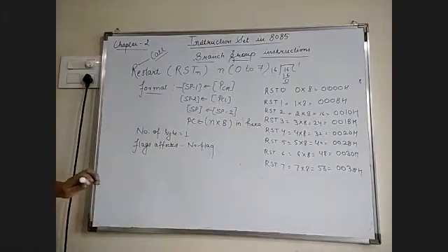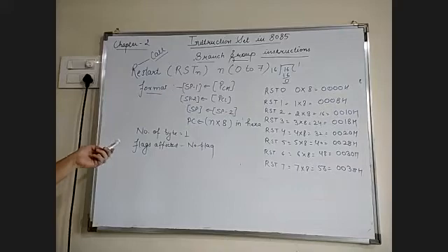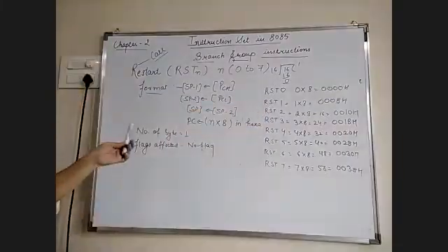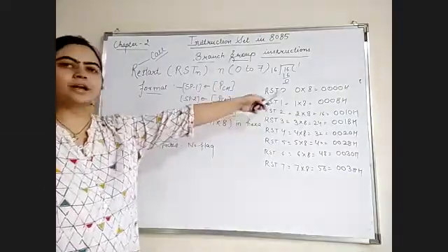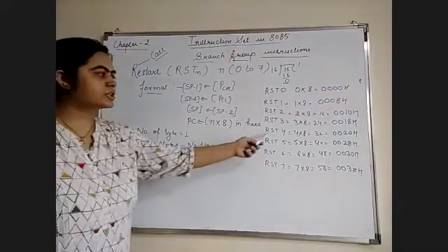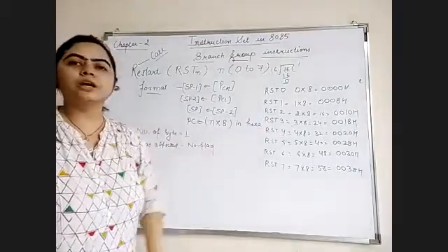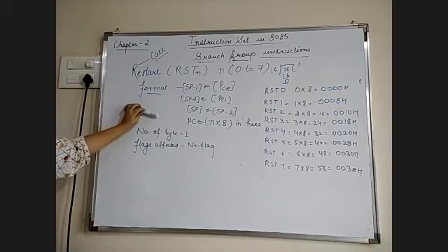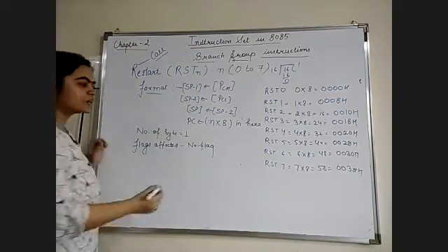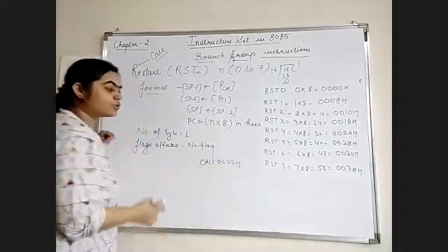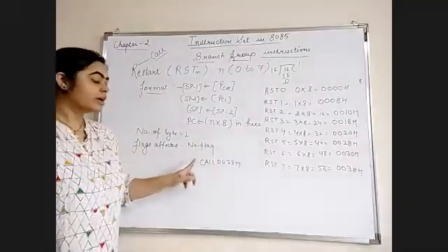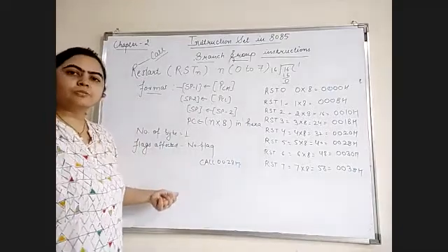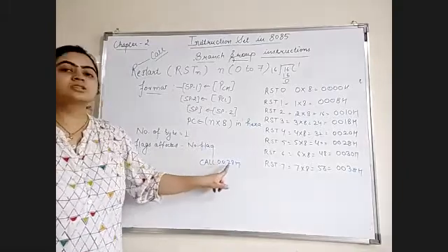Okay. So this instruction will transfer the program control to the specific memory location as shown in this table. When this instruction is executed, the program counter is updated with the new vector address which is given in the instruction. Suppose in a program we have an instruction RST5. Then the program counter is updated with the new address, and that address is 0028H. So it is used just like a call statement, but the only difference is with the call statement. If I write call 0028H, it will push the contents of the next memory location into the stack memory, using this formula. And after pushing the contents of the program counter, it will go into the subroutine program which starts from this memory location.